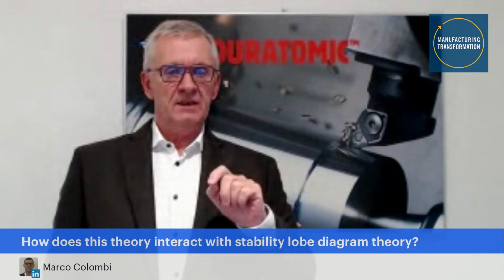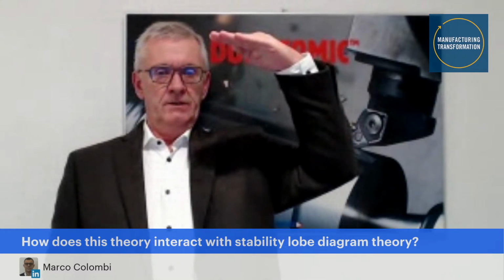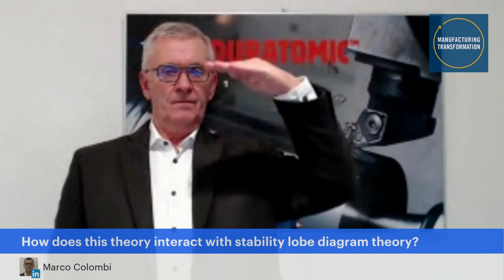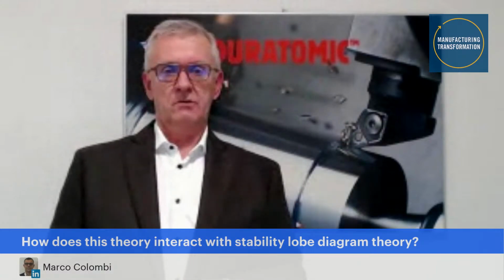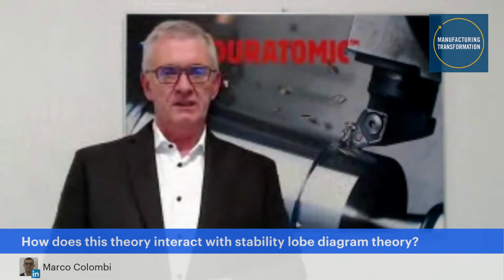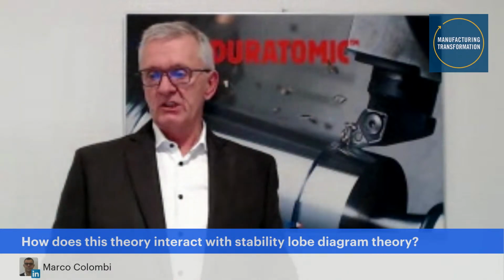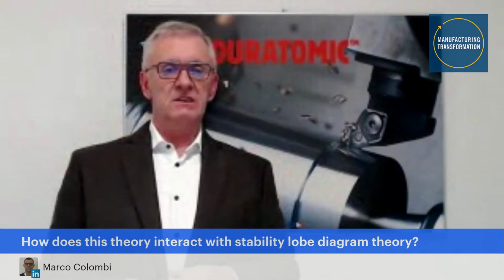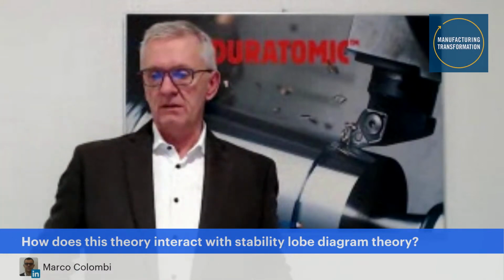A micro vibration is that a cutting edge on top of this movement does this. And that's a micro vibration. The official name is chip segmentation vibration. I think that's a little bit, I call it micro vibrations. But stability lobes of machine tools, resonance stability things, is a different thing. That has nothing to do with micro vibrations.